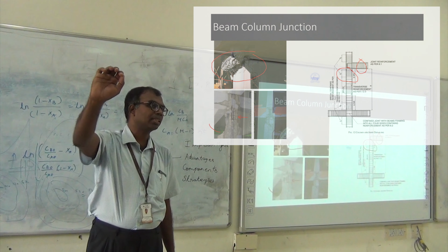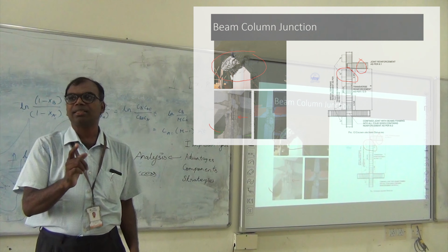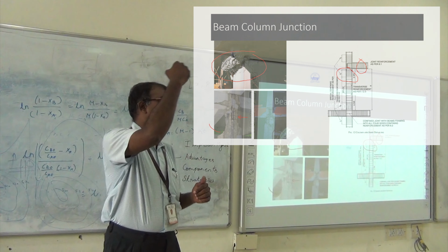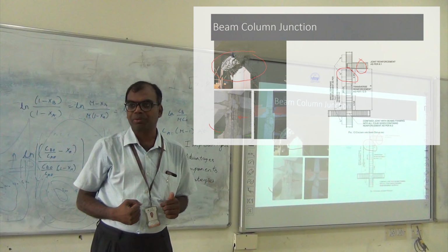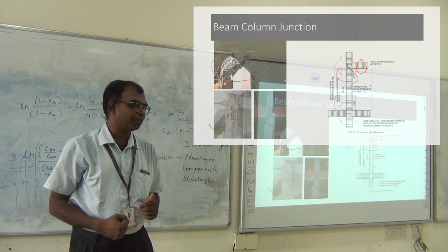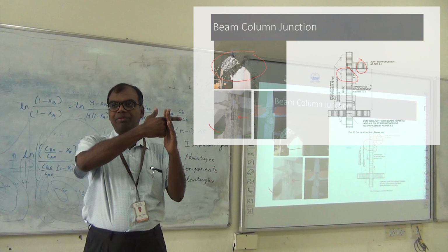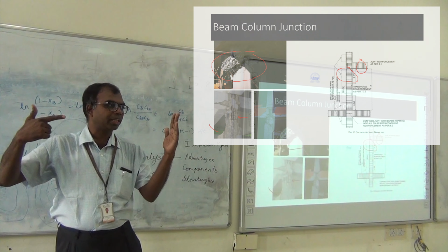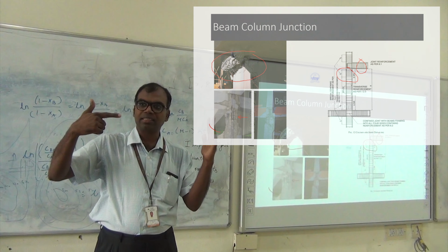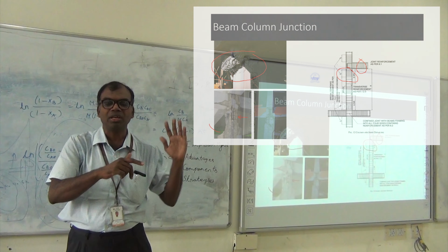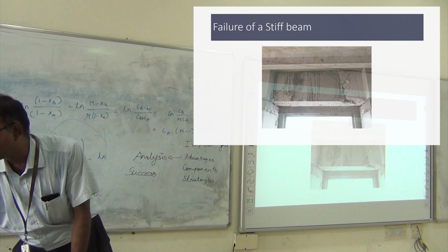The joints have to be detailed properly. In the last class we said the reinforcement rod has to go deep into the concrete, to a length we call the development length. If you don't put it deep enough, it is going to come out in the event of a pulling action, and reinforcement steel is only for tension. Now let us go a little further.